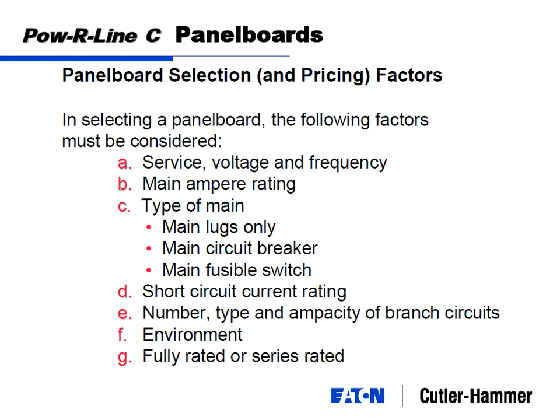This is the main bonding jumper between your neutral and your grounding electrode conductor. So that's very important. As a user, if it's your building, you'll probably never need to look at that, touch that, or even know where it is. The utility company, I believe, is probably the driver behind it. They may be the ones who need to come in and change something or remove that for some reason.